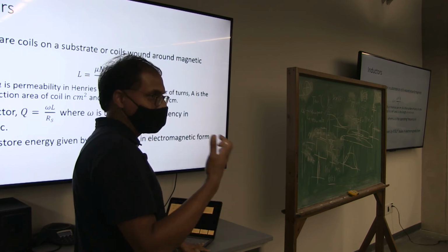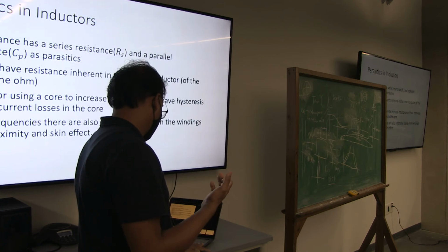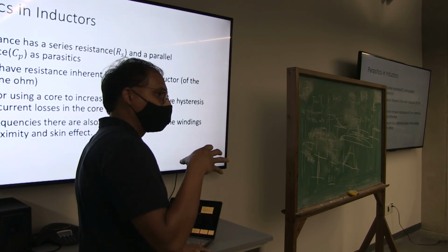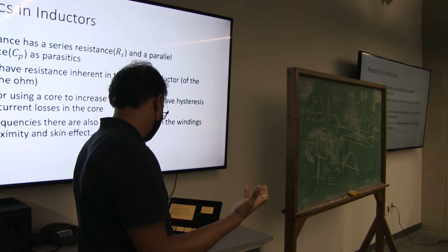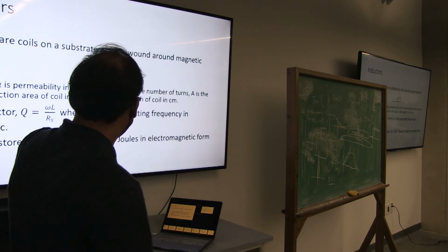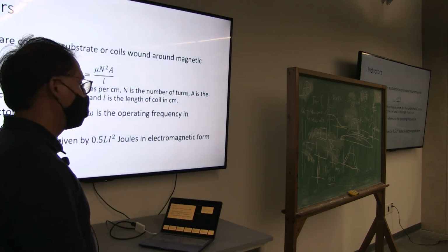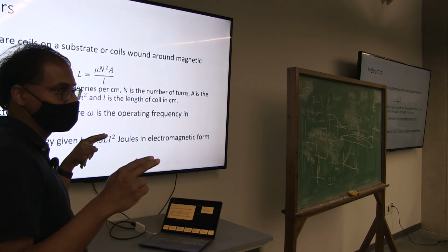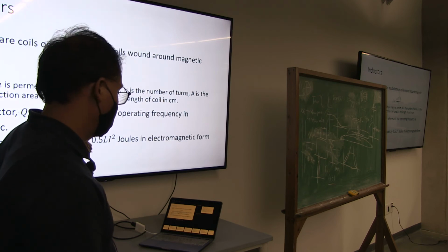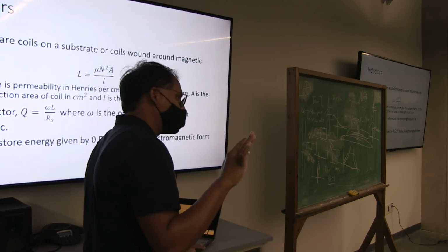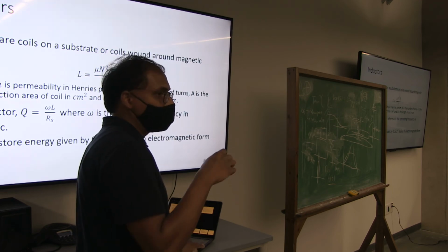Capacitors and inductors all have a quality factor, and again the quality factor is determined by the parasitics involved in the inductor and capacitor. If we look at the quality factor definition, if the parasitic resistance in the inductor is 0, then we have infinite quality factor, an ideal inductor. But typically the parasitic resistance is around 3 or 5 ohm, so that will reduce the quality factor drastically in an integrated circuit environment.